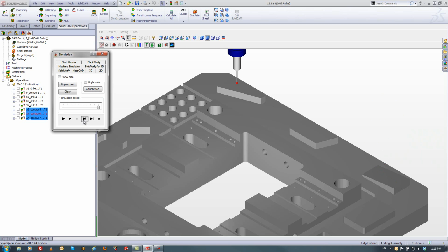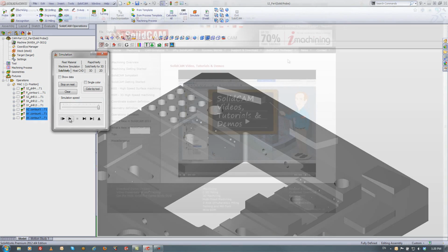Now it's going to come to the Y, move over there, touch off on that side over there. Now it's going to go back up and touch on the X angle as shown over here. Now, since I told it to touch off twice and repetitive, you see it's doing it twice. And that's how we measure our X, Y, and Z angles.